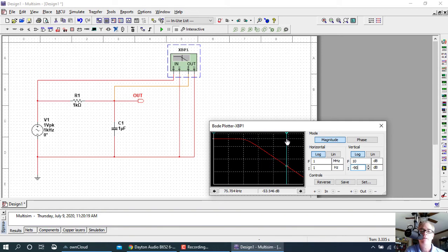So as I go up in frequency, which is what I'm doing now, and you can see what frequency we're currently at, you can see that the output in decibels is now much lower. So we started out at 0 decibels, and now we're at negative 61 decibels. You can change that. I mean, I don't know if the Bode Plotter here lets us do that. And it doesn't. It's going to keep the answers in decibels. But on some spectrum analyzers, it'll allow you to see the answer in voltage or some other magnitude. But decibels is by far the most common.